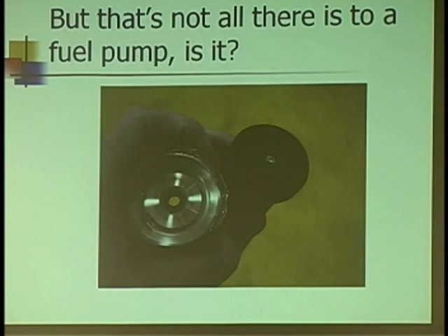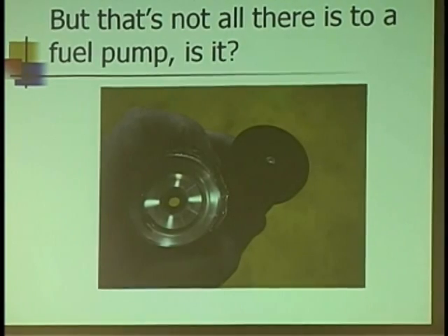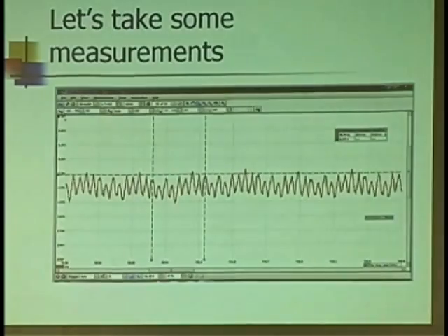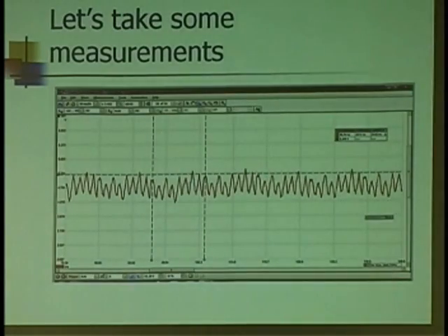Yeah. That's the intermittent one: driving down the road, it starts sputtering like you're running out of gas. You sit on the side of the road for 30 minutes and you can drive a while again before you run out of gas again. So if I want to make more use, not just of the electrical health of this pump, but if I want to get some diagnostic use out of this, I need to take a few measurements. I'm going to measure the time it takes for one segment to complete, and of course I'm going to measure where the current draw is.